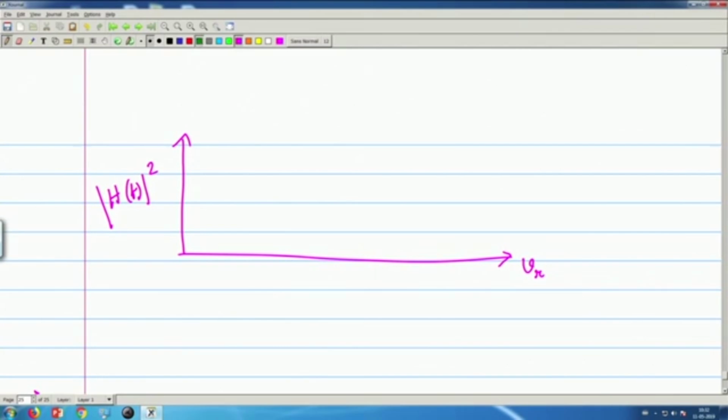So, the graph will be, there will be some initial kinks, but otherwise that will be a flat response up to the first blind speed. So, clutter is removed, you see first blind speed pushed away and more or less uniform response over MTI passband. So, this is a good way.